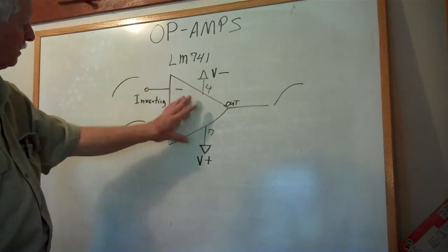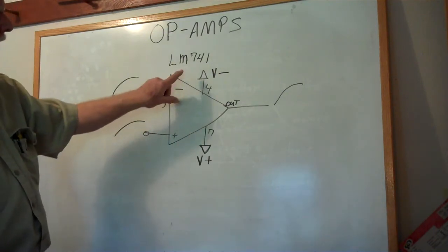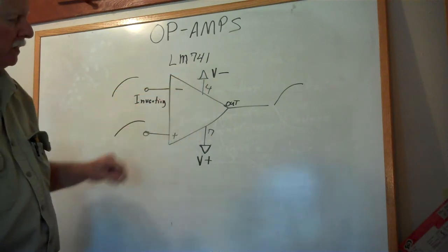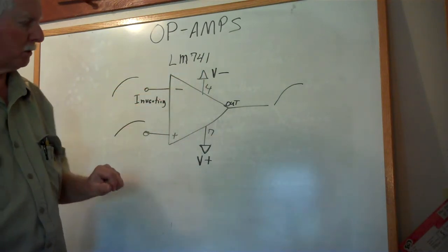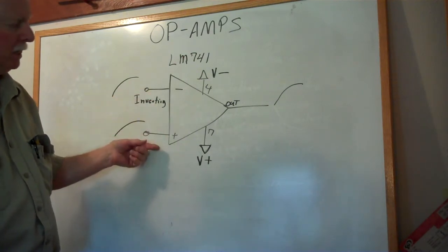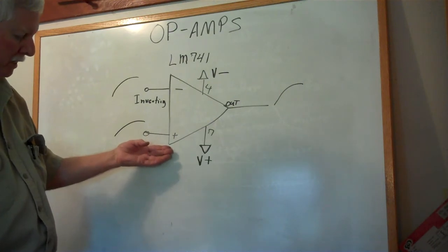They're very much isolated because of the high input impedance of the JFET amplifier, as opposed to the lower input impedance on the LM741. Even though it has an input resistance of 2 megohm, sometimes it's desirable to have a much higher resistance. And that's where JFET and MOSFET type op-amps are important in those kinds of signals.